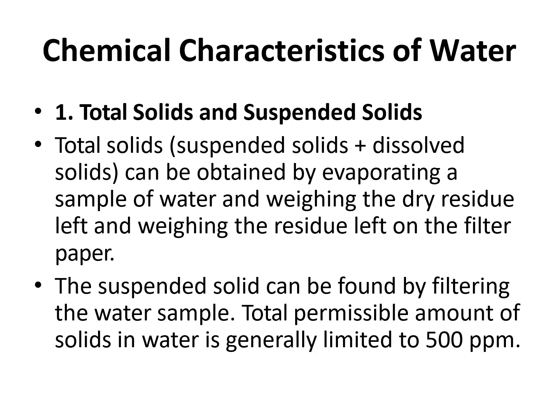First one is total solids and suspended solids. Total solids is the sum of suspended solids plus dissolved solids. The suspended solids can be found by filtering the water sample. It is denoted in ppm, parts per million. Normally, the total solids and suspended solids are limited to about 500 ppm.